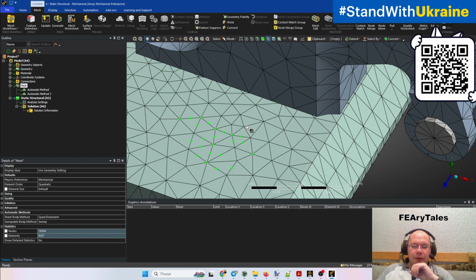If you have a multi-body part, it will be a very bad solution if you create some bodies with second order elements and some bodies with first order elements, because some of the mid-sides on the border between those two bodies will partially fly in the air, fly in the space.